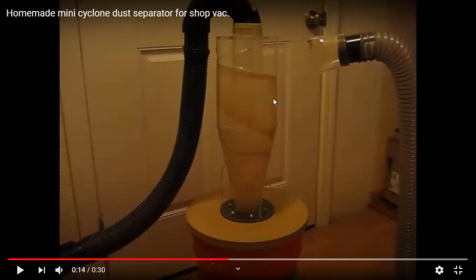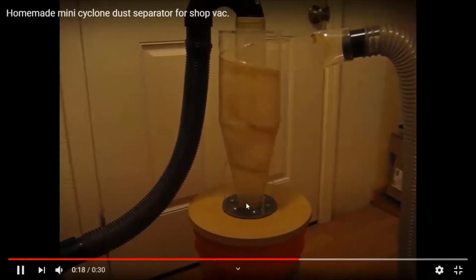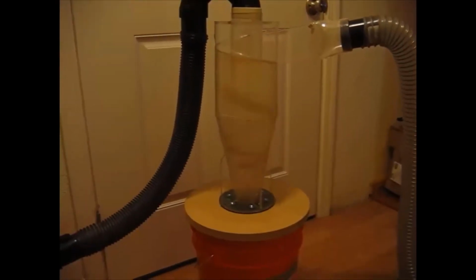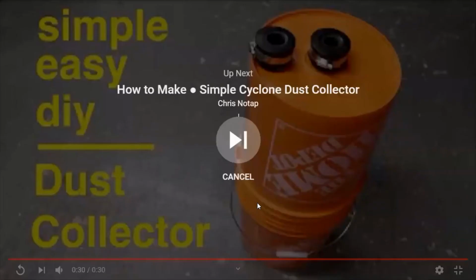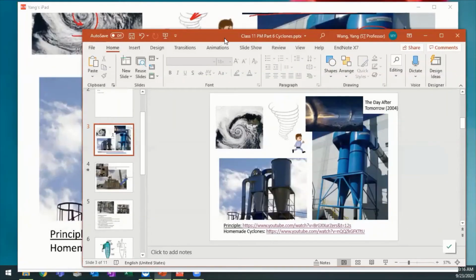So they flow like a ribbon, and then they just stack on each other, right? Then finally, when they get to the bottom where there's a cone, they have to get compressed. And then this is the outlet, right? So the air is withdrawn from the top. Yeah, so this is the basic principle of a cyclone.